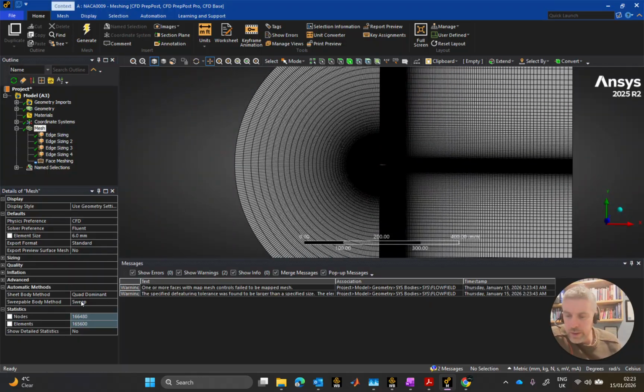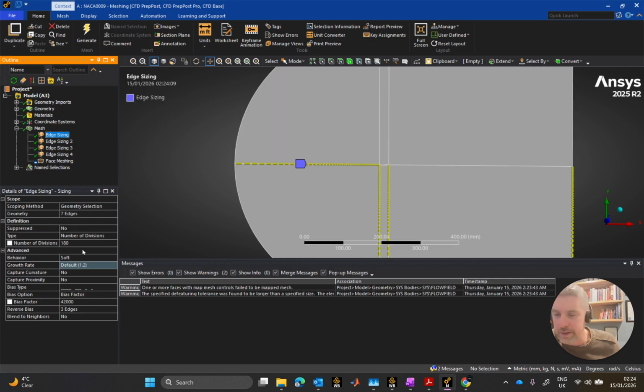So I'm going to create a finer mesh where I increase the amount of these cells, and a coarser mesh where I reduce them, and see how we go on. So how am I going to do that? I don't want to have to come in here and take everybody through the exercise of clicking in here, changing it, blah, blah. So what I'm going to do is take a couple of metrics out of this. I'm going to click on this white box and make a parameter out of that.